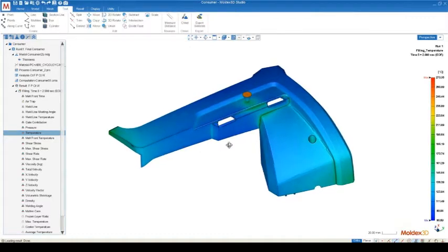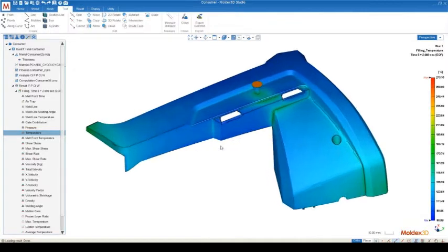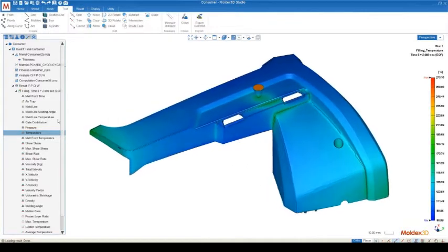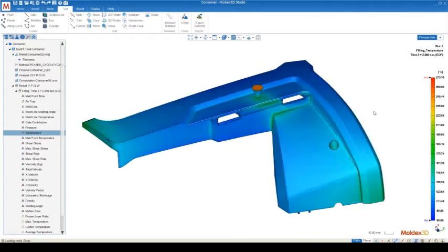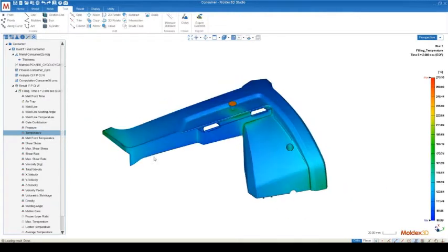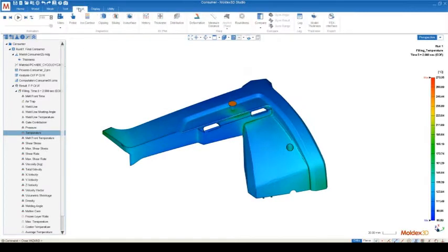In this case, this is actually a really good case to demonstrate a bad processing time. Through the temperature result, I can really get an idea of where my hot material is located. If my hot material is located at my gate, that means the cooling effect dominated. If my hot material is at my end of fill, that means the friction effect, or the shear effect, dominated. So we can actually tell where the hot material is pretty easily through results.